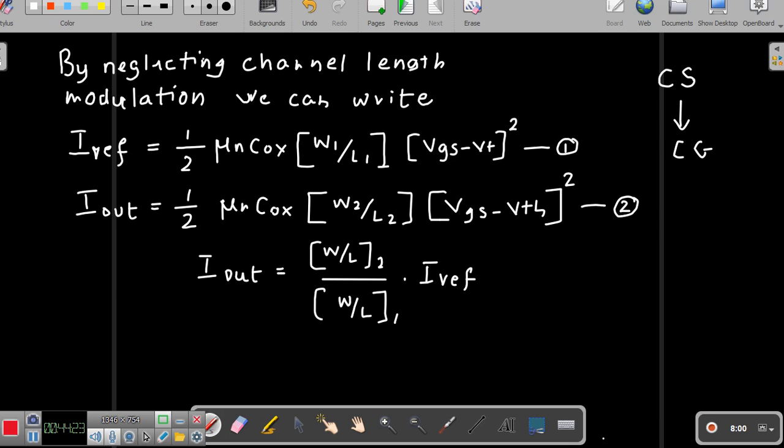I will tell you what exactly this is. This is not cascade, right? You know the literal meaning of cascade, but it is called cascode. It is connecting the common source stage of a MOS device with a common gate stage. By connecting so, in what way we will be able to overcome the effect of the channel length modulation, and what other advantages and benefits we are going to get by connecting two transistors in the cascode stage, that we shall probably see in our next presentation.